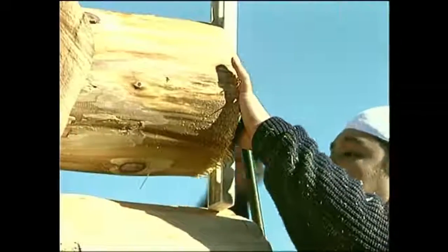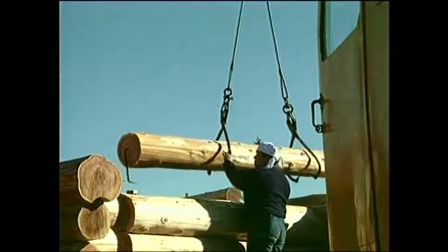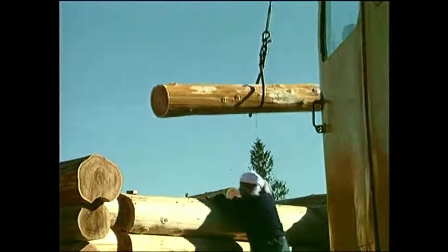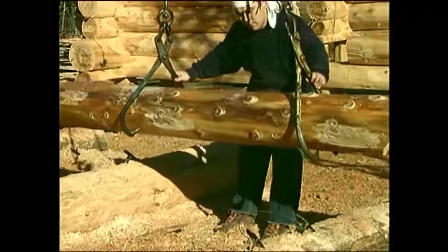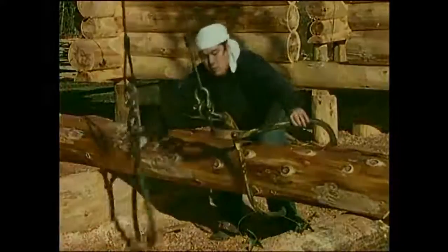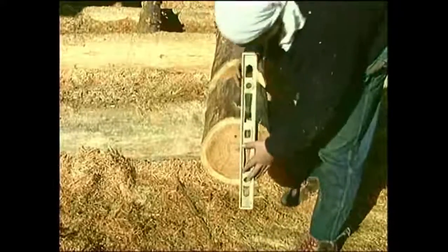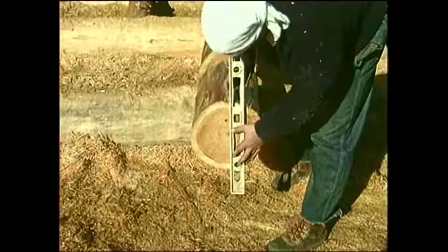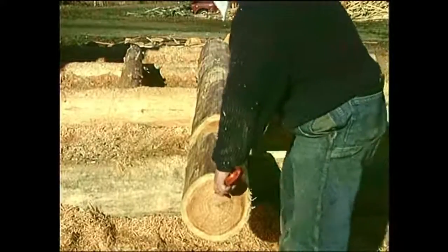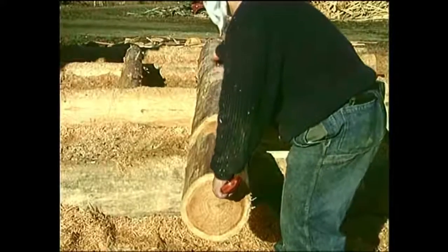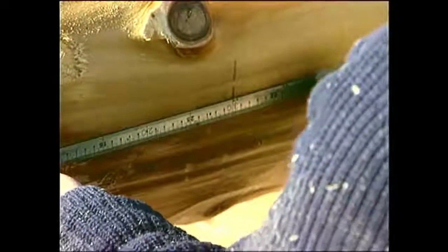When the rest of the scribe has been completed, remove the log from the wall and place it for cutting. Before you cut out the groove and the top of the window opening, snap a center line onto the bottom of the log and use this to bring the cut lines across at right angles. The cut line can be located in a very standard and accurate way by using two squares on the center lines.